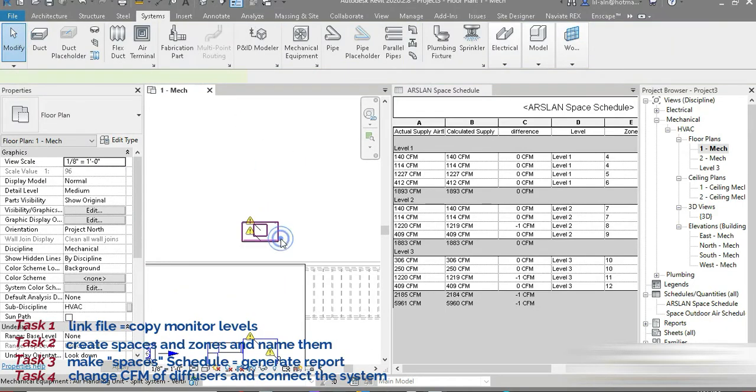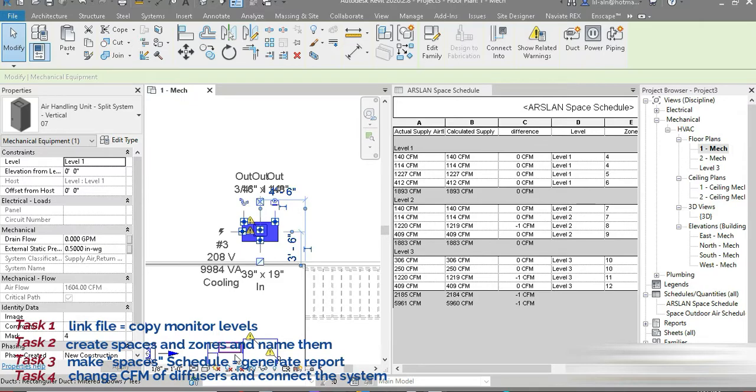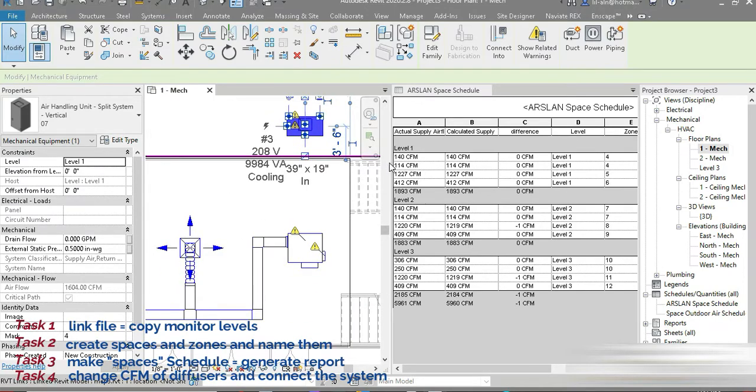So the capacity of the AHU unit has to be enough to sustain the 3 VAVs, right? So the total of the 3 VAVs is 5960, isn't it? Because this is the total of first floor VAV, this is the total of second one. So in a way, your diffusers have to be according to the calculated values. Your VAVs have to have enough capacity to sustain all of the diffuser values, which is 1893, and then your AHU has to be powerful enough, or you could say it has to match the CFM of the three VAVs, right, which is 5960. I think that is perfectly explained.